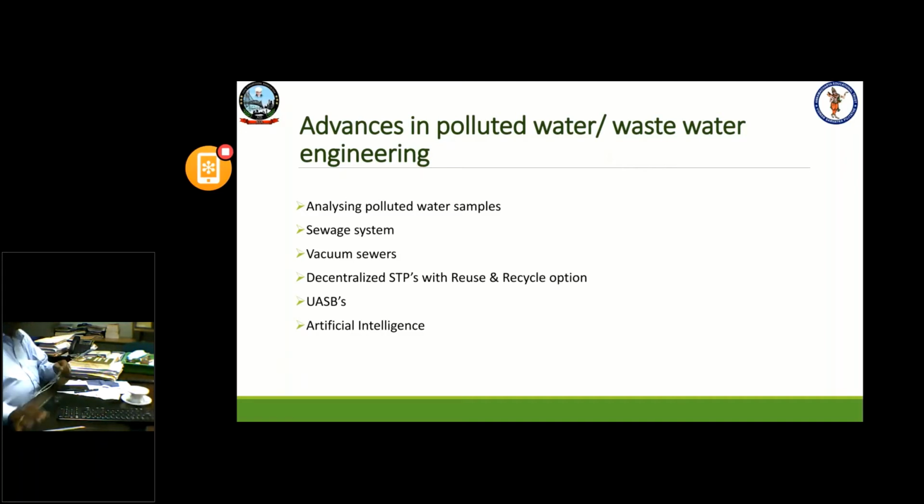So all this sewage goes from the household or building to the streets, and the next line is to the roads, and is taken up to the treatment plant. The laterals are used for collection of sewage from the household, intermittent sewers take it up to the roads or highways, and again we utilize the trunk sewers to take the wastewater up to the treatment plant.